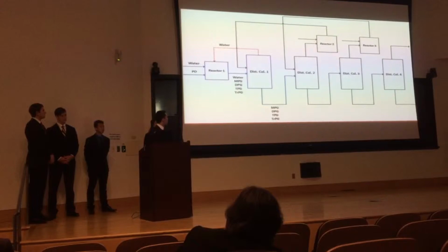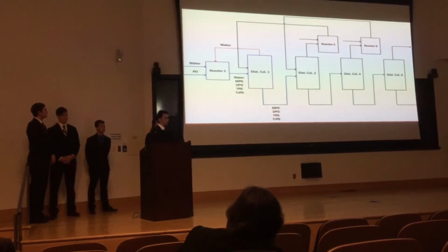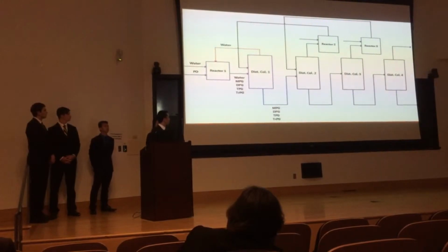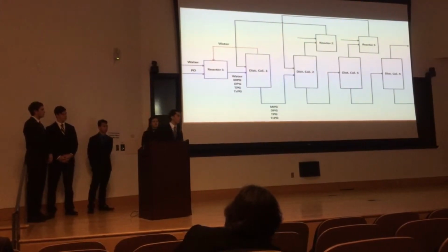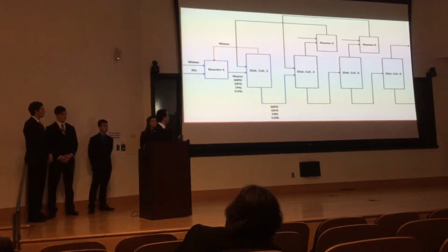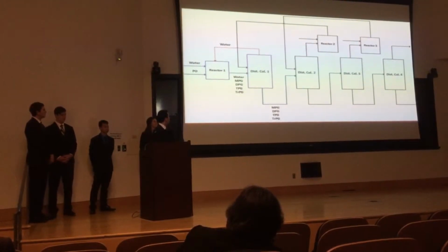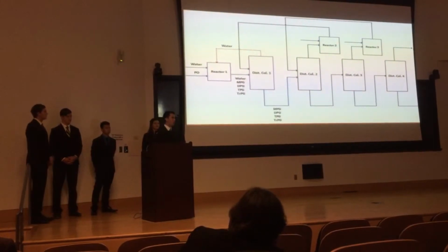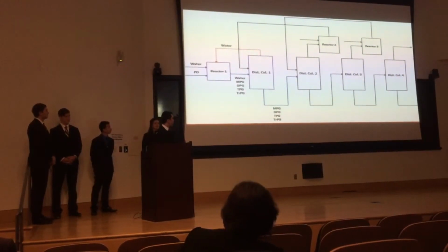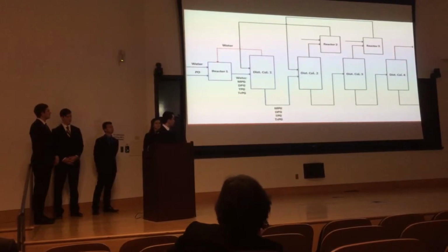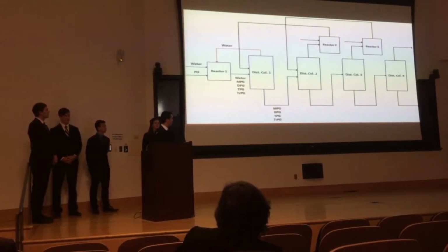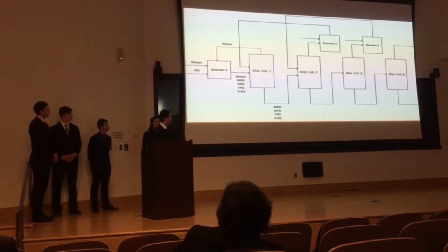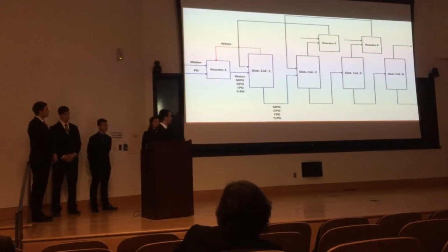We also have water left unreacted from the first reactor, and we feed that stream into the first distillation column. On the top of the column, we separate water, and that water stream goes back to reactor number 1. On the bottom of the column, we have glycol products, from monopropylene glycol all the way to tetrapropylene glycol. We then feed that into the second distillation column.